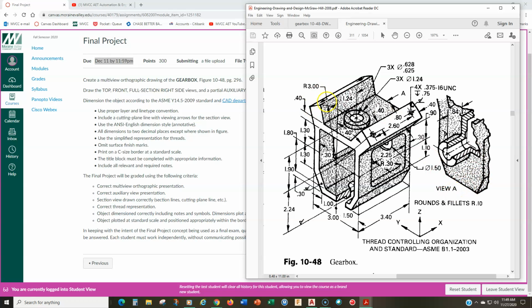The tapped holes, in fact, they're tapped blind holes or blind tapped holes, depending on how you want to phrase it. There are 4 of them, and they're right here, 2, 3, and 4. So there's 2 each on these angled surfaces. All right. Now I should point out, and I don't feel like I'm giving too much away here, these angled surfaces have a curved top. So the top of this inclined surface, and the top of this inclined surface, have a slight radius to them, and the radius is in fact a radius of 3 inches measured from the center of the box.